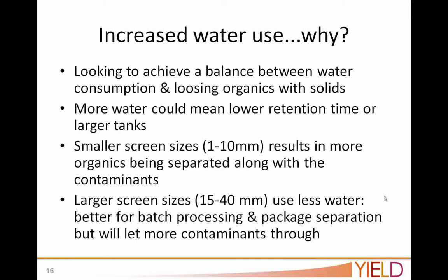So let's say, for example, you want to take pre-processed material at a facility, or you intend to utilize pre-processing on site. You need to think about how big your tanks are, because if all of a sudden you're adding 50% water to your feedstock, now you have this volume, and what are you going to do with it?